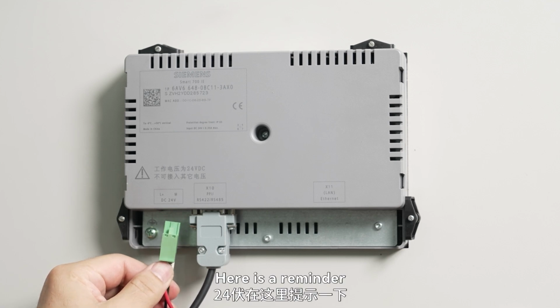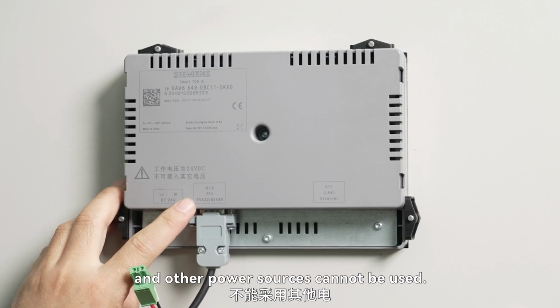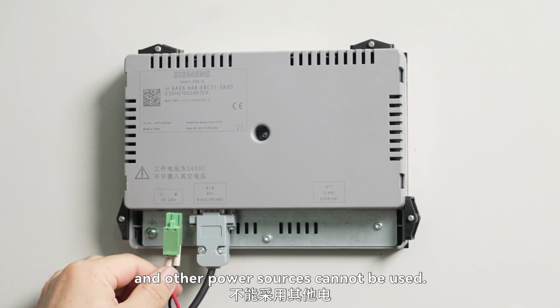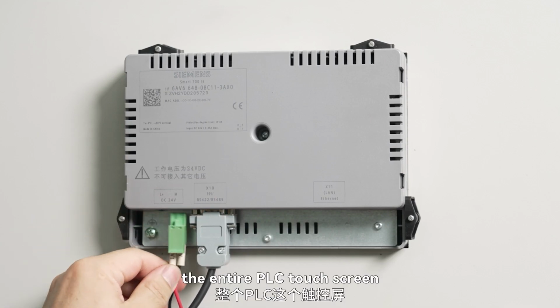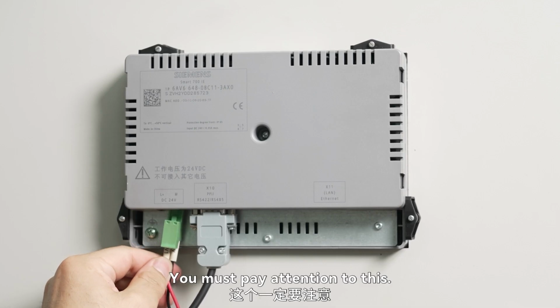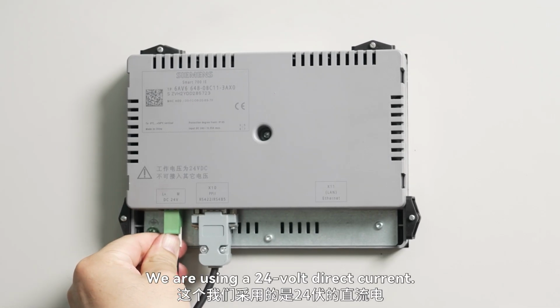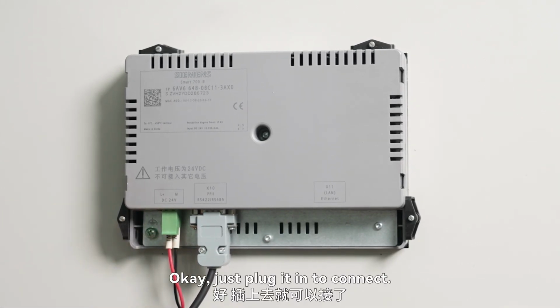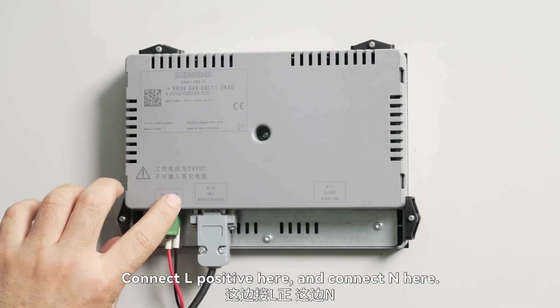Here is a reminder that the working power supply must be 24 volts, and other power sources cannot be used. If you connect alternating current, the entire PLC touchscreen will be burned out and become useless. You must pay attention to this. We are using a 24-volt direct current. Okay, just plug it in to connect. Connect L positive here, and connect N here.